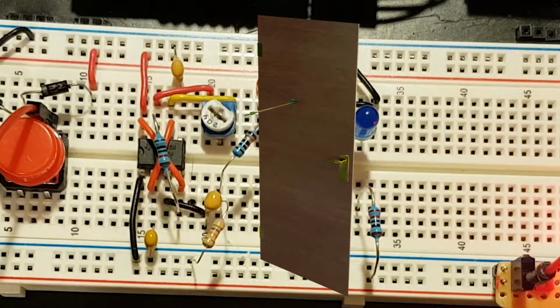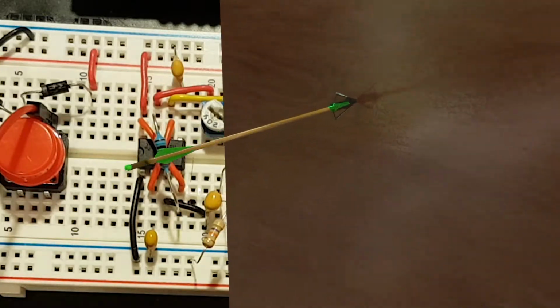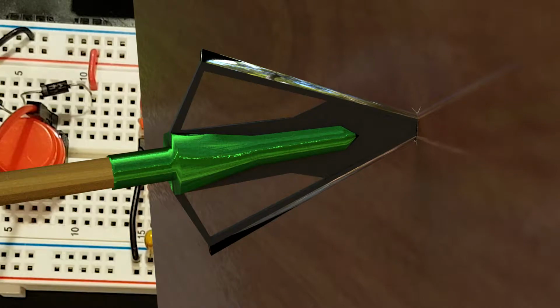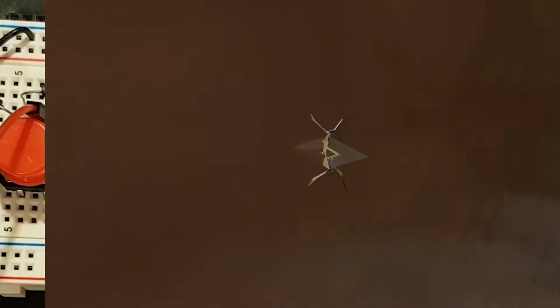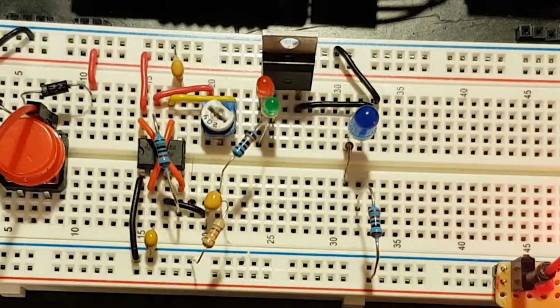If we go back to our arrowhead analogy, remember we said the arrowhead conducts electricity and the door blocks it. Because the tip of the arrowhead has poked through, there is a tiny area where a small current can flow back through. Every diode can leak a tiny amount of current through the wrong way, but it's so small it's almost insignificant. You do have to be wary with the Schottky, however, as it's enough to affect some circuits. Due to this faster switching, Schottky diodes are also used extensively in switch mode power supplies, where frequencies can go as high as 2 MHz.